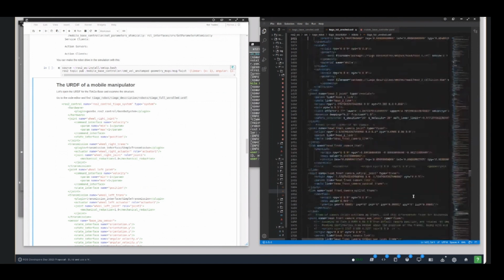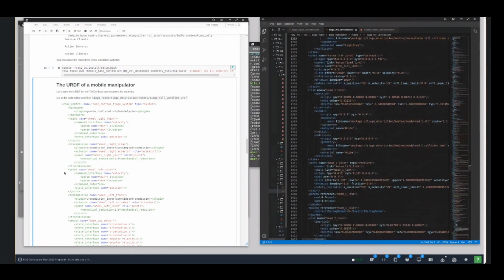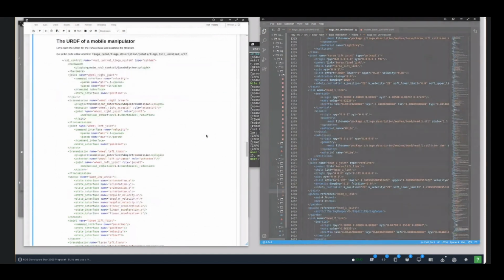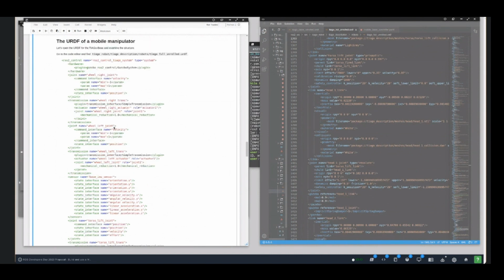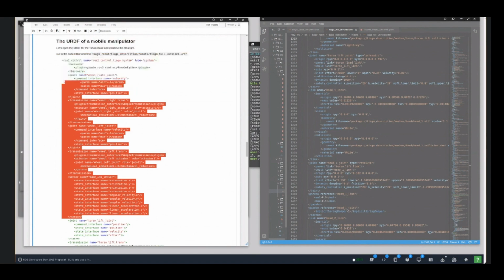I am going to go ahead now and switch back to the left again. So this is basically just to prove that now in theory we have a setup where we have added these. On the left side, you can compare to the previous much simpler version. This version of the ROS2 control tag includes every single joint of the previous setup, which was the mobile base.